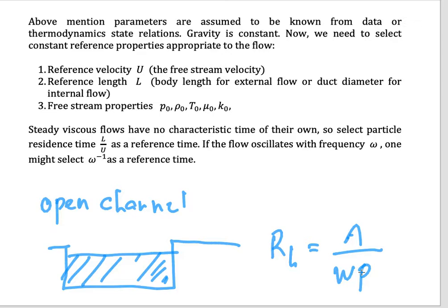because sometimes I found that people take a wrong parameter to make the calculation. Okay, first is the geometry of that object, and then the second one, for sure, is velocity. In fluid mechanics, if the fluid is not moving, the pressure will not occur, the force will not occur. So it's just fluid static, for example the buoyancy. If you have a boat in the ocean, that is only about fluid static. If the boat starts moving, the fluid is actually moving relatively, or flowing past the boat.